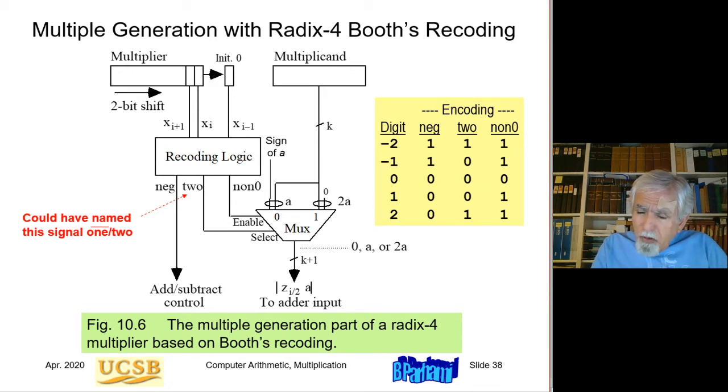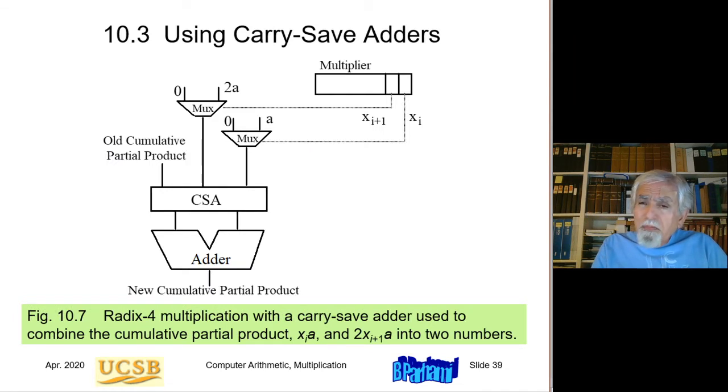It turns out that in most cases, and we can't prove this, it is highly technology dependent, but in most cases, this scheme is better because it's using multiplexers that are pretty easy to implement in CMOS. And carry-save adders are nothing but a bunch of full adders. And full adders are circuits that have been highly optimized over many years because they're such useful building blocks that people have come up with many designs that are fast and low power.